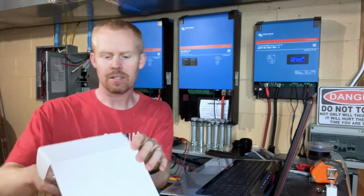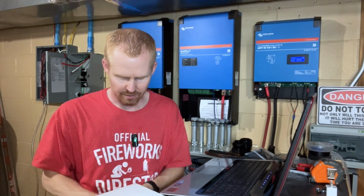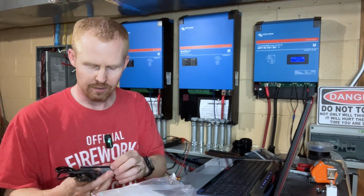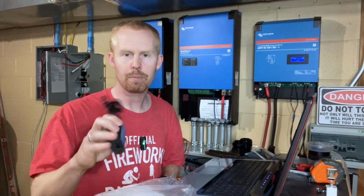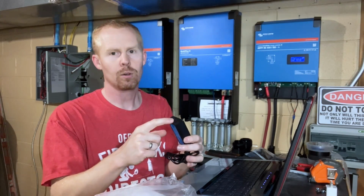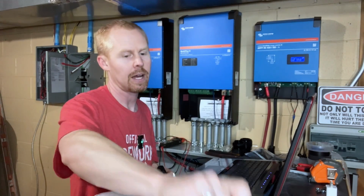You have to get a separate device specifically for these inverters, and this device is the Mk3 USB, VE Bus to USB. So your USB will go into your computer, and then any old Cat5 cable will connect from here into the VE Bus port on the inverter.